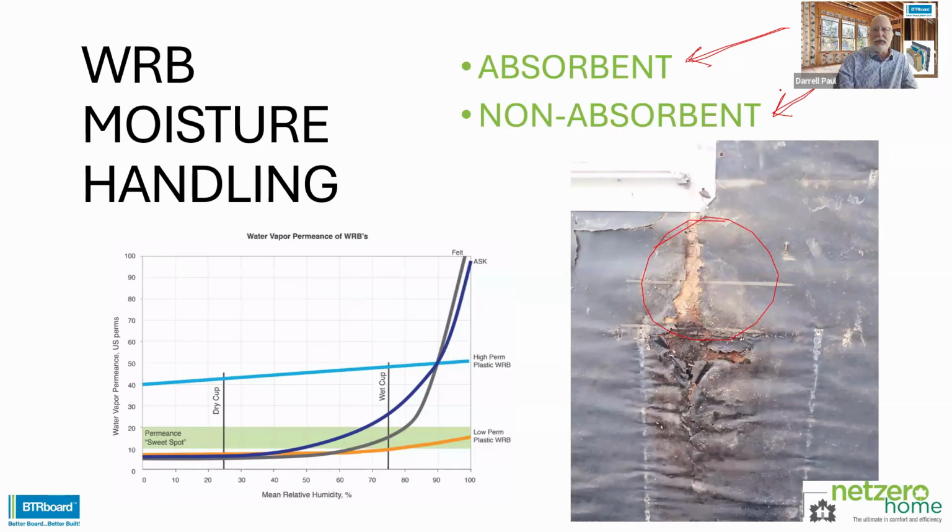But one of the other things to keep in mind with the synthetic materials is you'll notice down here, and this is a great illustration out of the document that's coming up, that basically when you're looking at materials like stucco or materials that can absorb water, when those get into a situation where the sun is beating on them after a rainfall, if they have really high vapor permeance, and we always talk about this as being better in a house, we want to have a house wrap that's really high vapor permeance to let lots of vapor through.